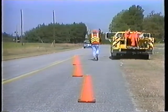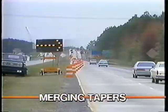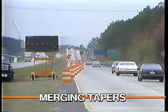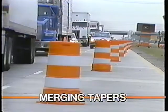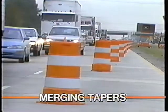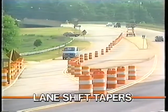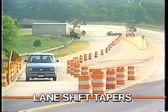There are 5 general types of tapers used in traffic control zones. Merging tapers close a lane of moving traffic on multi-lane highways where a merge is required. The spacing for channelizing devices should not be greater than the speed limit. Lane shift tapers move traffic to a different lane where a merge is not required.